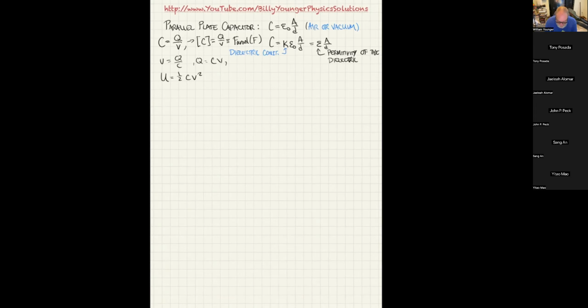So now I can also say, like I did before when I was talking about power equals current times voltage, you could use Ohm's law to replace the V or to replace the I. Well, you can use the definition of capacitance to replace various things. So for instance, we could go ahead and replace the C with Q over V, and then you'd get 1/2 Q times V, because one of the V's in the bottom would cancel out.